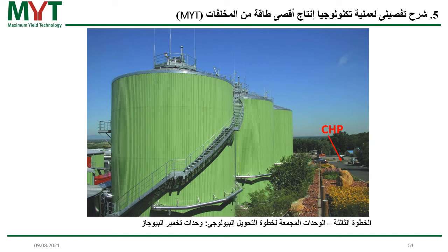And that means for you that if the process is slow and if this material has to stay for a very long time in the fermenters, you need more volume and more fermenters. And also if you put solid material into fermenters, you have much more cleaning efforts than if you only put process water into the fermenters. So it's much more easy to handle. And in addition, you have a great yield in methane.